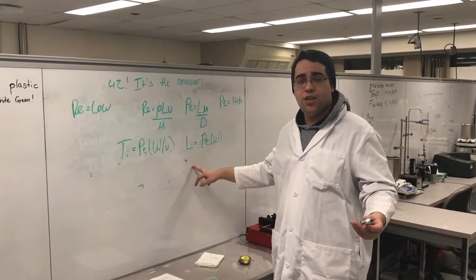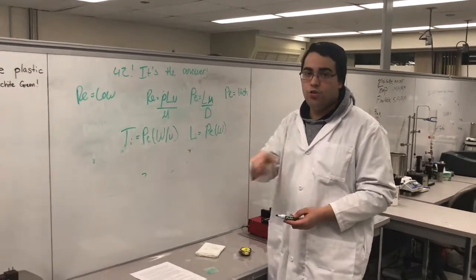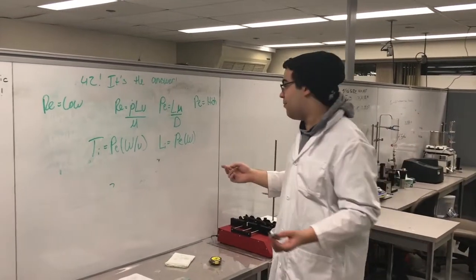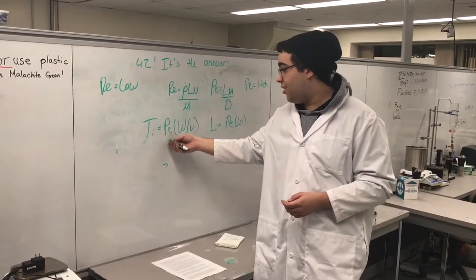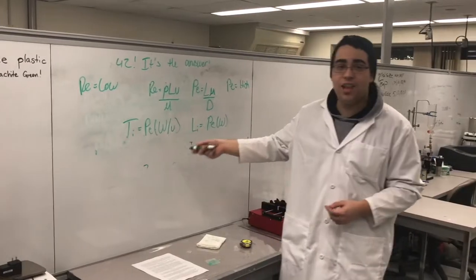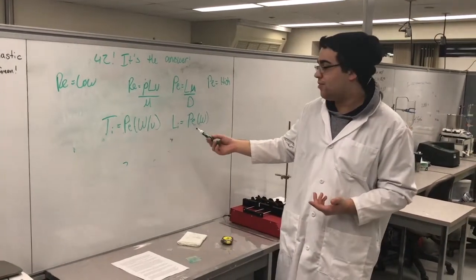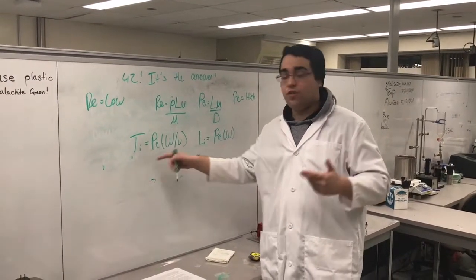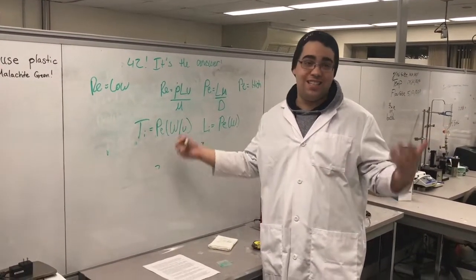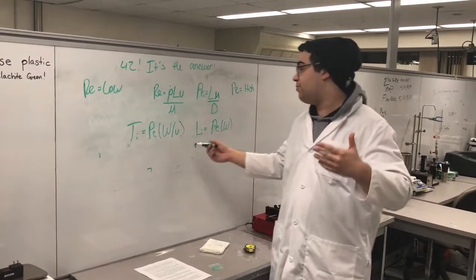Knowing that diffusion is the driving force in our microreactor, 2 equations will help us determine our desired dimensions. The first one, known as T ideal, relates the Peclet number times width and the velocity of the fluids in the system. This equation will tell us how long the Mg and the NaOH need to flow through the system in order to get the ideal time needed for complete conversion.